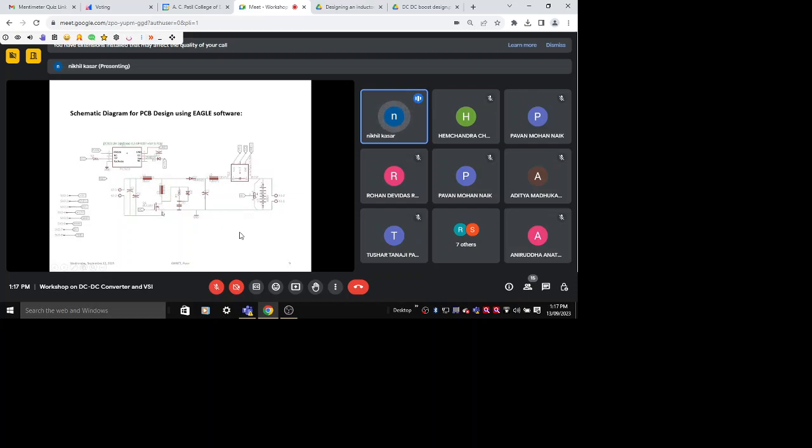Its source is at the reference potential. So we can use a low side driver. So this is the low side driver. Now with respect to this source, you have to apply a 15 volt PWM pulse at the gate. So this source must be connected to this ground. Okay. This ground and this ground must be the same.